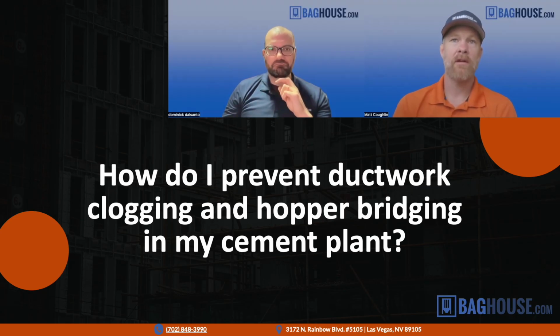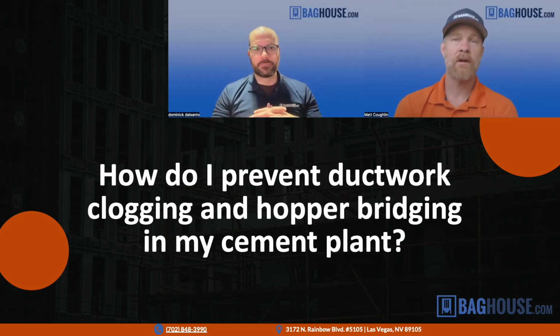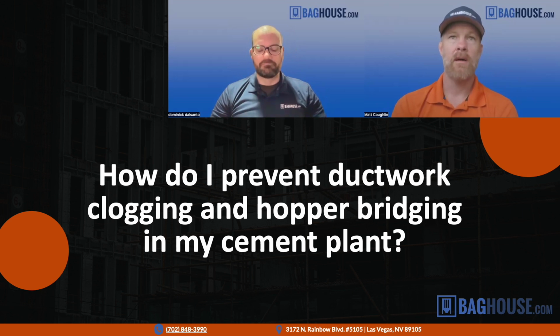And then another good practice is just to have clean out doors and access panels in your ductwork, so that as part of your quarterly inspection process, you can go look in your ductwork and see if you're getting dust settling, vacuum it out if you need to, and just make sure you're keeping tabs on it before it becomes a big issue. Nice. All right.